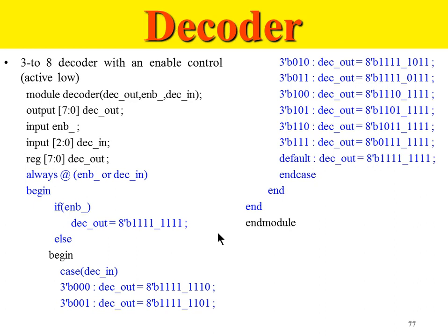The non-blocking assignment mimics the hardware correctly at a simulation level. Why do we do simulation and then go to synthesis and backend implementation? The simulation should show the same behavior your hardware design shows on the board. So when you use non-blocking assignment, the simulation will show that delay, similar to actual hardware.